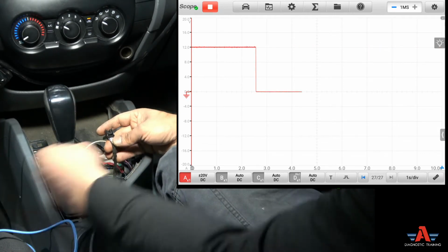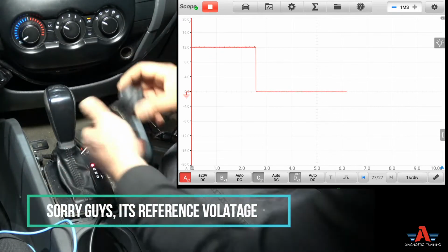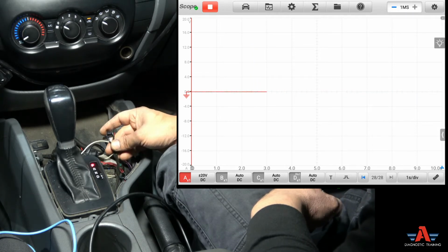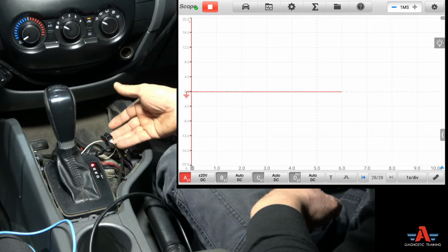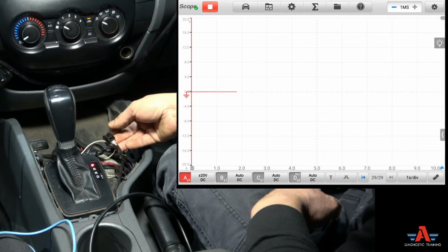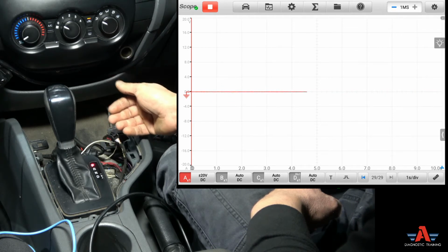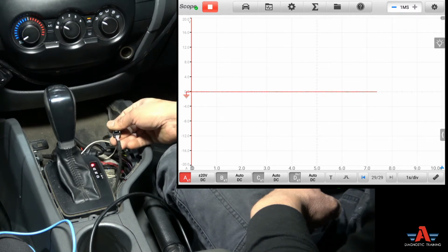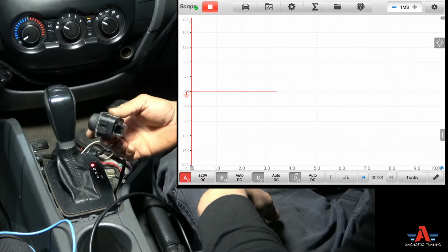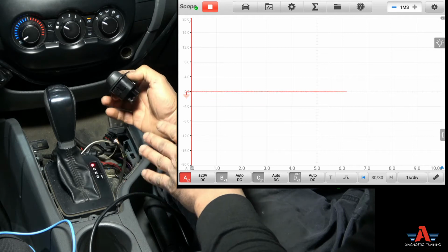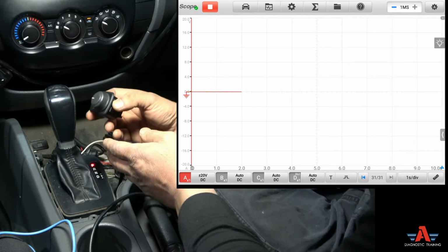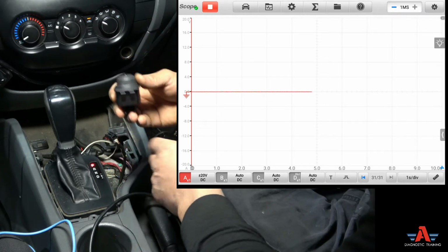Now how this is going to work is, before that already, just by checking that, we already verified all our wires are good up to here. There's no need to check for powers, earth, computer, nothing at this stage. More than likely, because we got everything that we need to see here, the problem is the switch. If it's a quick diagnostic, I would say that's it, we need a new switch. But just for learning purposes, I will go further and teach you guys more stuff here.